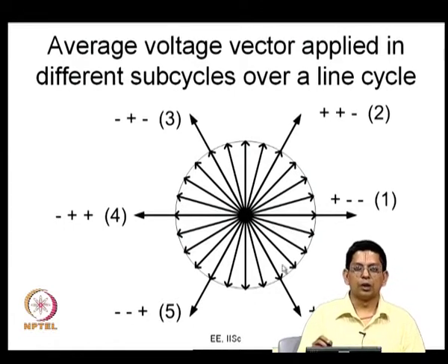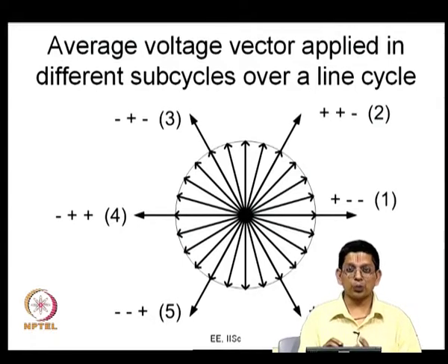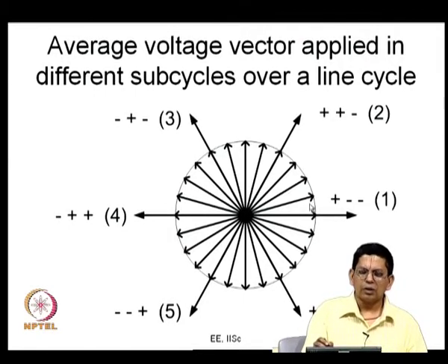So, what I am doing is I am going close to a rotating voltage vector. What am I supposed to produce? I am supposed to produce 3 phase sinusoidal voltages, and in the space vector domain 3 phase sinusoidal voltage is nothing but a revolving voltage vector. I am supposed to produce a revolving voltage vector. So, that is what I am doing. I am producing a vector like this which stays there, and after a short interval it moves by a small step, it stays there, and after a short interval it moves by that.